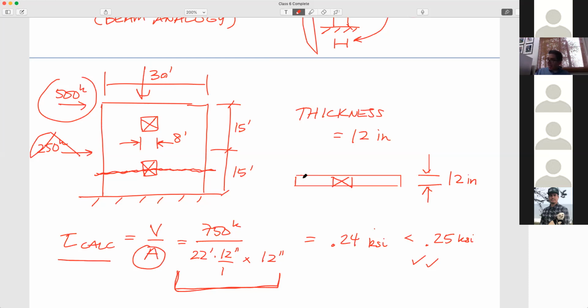So when I say the area and we do the shear calculation, we're going to do V over A, and A is, I'm even going to do a different color. I would jokingly say no extra charge for that extra color. And then that would be the area. That's the cross-sectional area of the beam where the window is present, making a void. So that's why I don't use 30, but I go 30 minus 8, giving me 22.